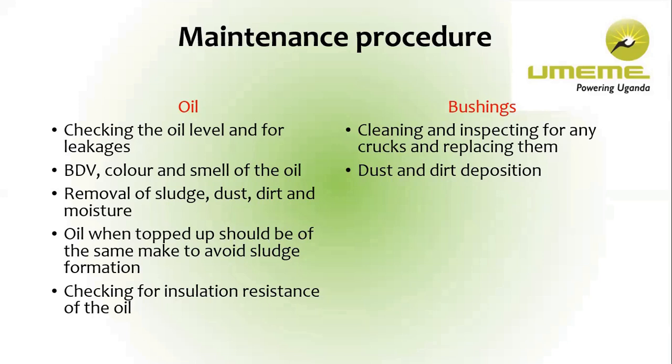So you check, you clean them. Cleaning is so much important because the moment there is any dirt, if it keeps on accumulating, it can act as a conductive path for voltages, for currents. If you find them broken, you replace them. Dust and dirt deposition, that's what I'm talking about on the bushings.